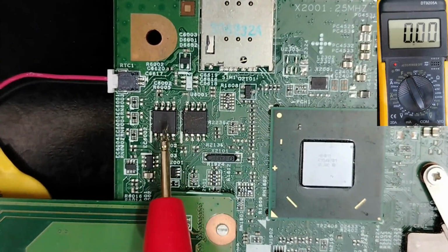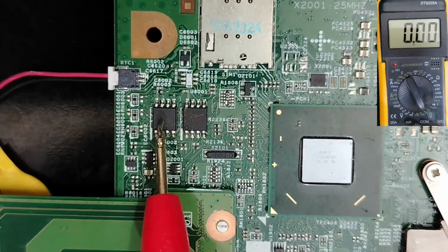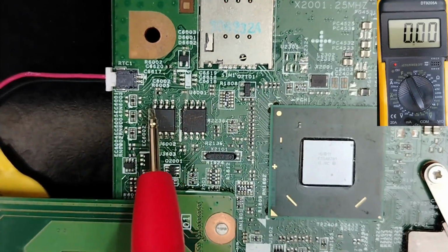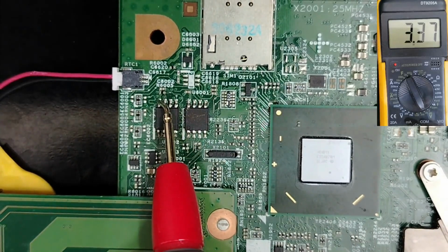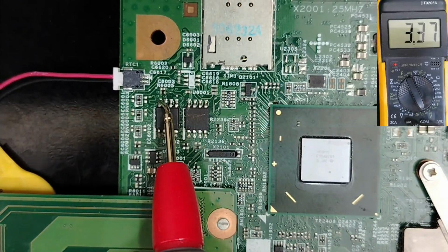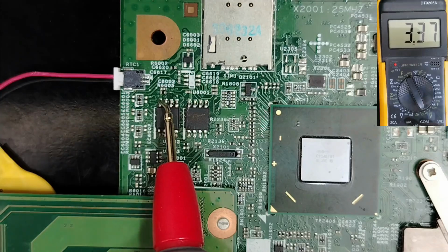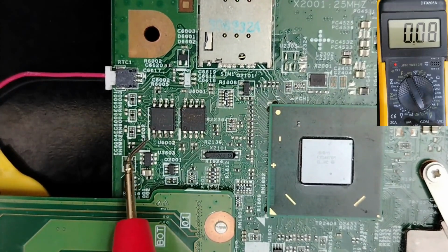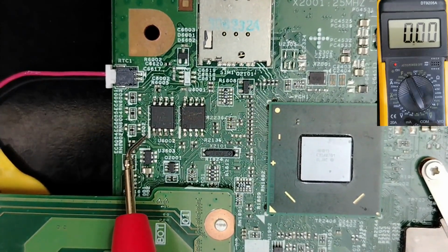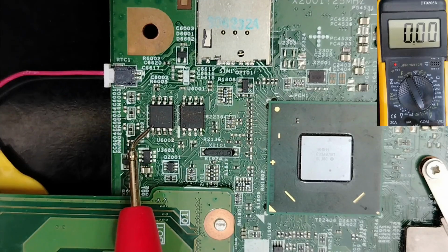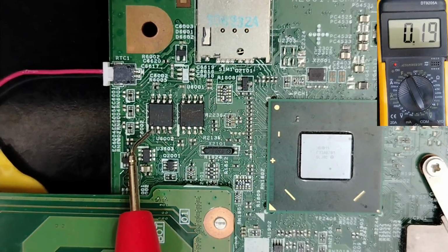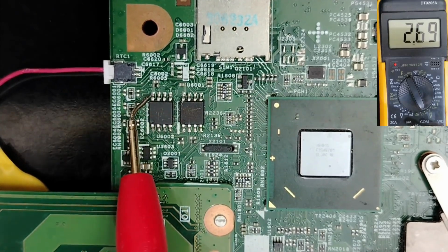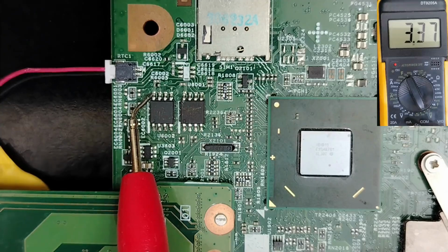So basically, to check if the BIOS chip is receiving its voltage of 3.3 volt, we can just check pin number 8. We have 3.3 volt. Good. We have 3.3 volt. Why? For beginners, why is this one pin number 8? As you can see, we have this white mark here. We have this dot over here, which means this is pin number 1, 2, 3, 4, 5, 6, 7, 8. Okay, guys, we have 3.3 volts, which means the